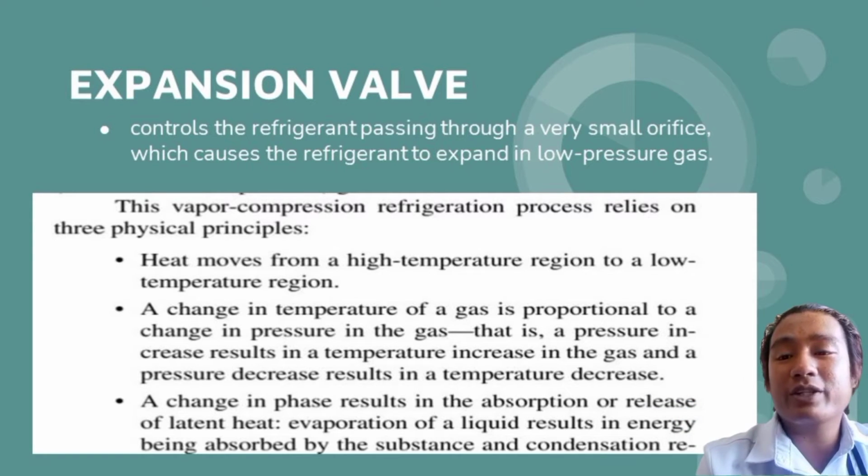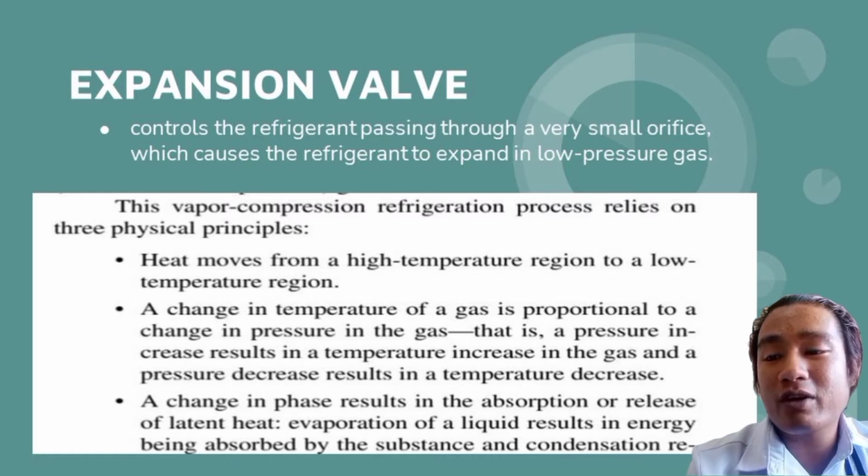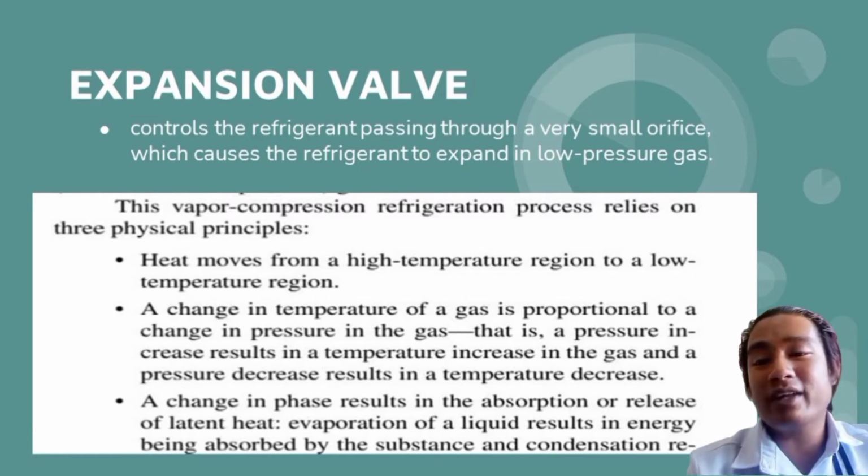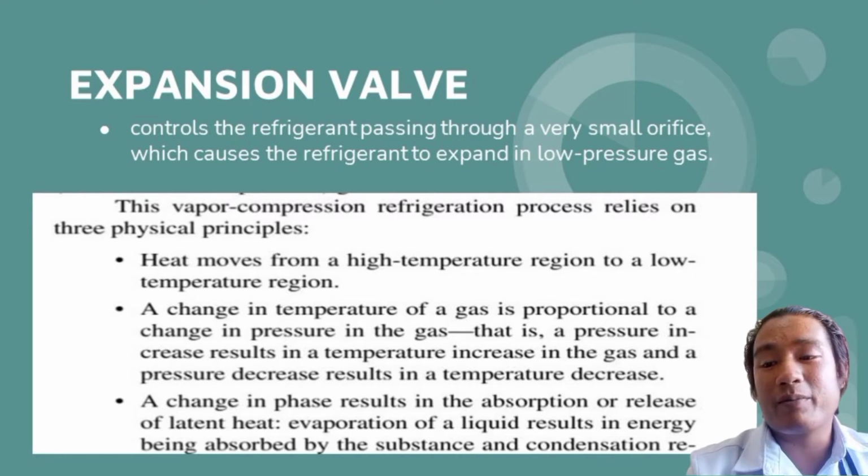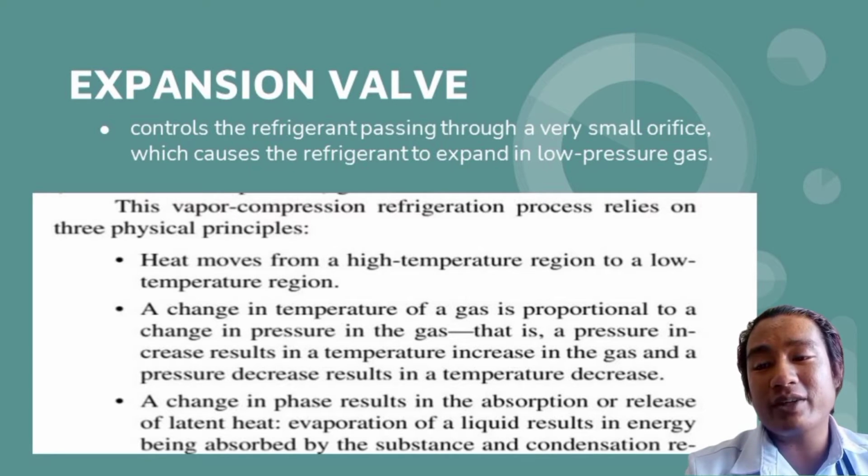Now, this is the vapor compression refrigeration system. The system contains liquid refrigerant that is forced through an expansion valve, causing it to change into a low temperature liquid. The low temperature liquid flows through the evaporator coil, cooling the coils and extracting heat from the recirculated room air or indirectly from a recirculated liquid medium, chilled water, that is used to cool room air. As heat is extracted, the refrigerant absorbs energy, increasing its temperature and converting it to gas. Then the warm gas is drawn into the compressor, where its pressure is increased, causing the temperature to rise.